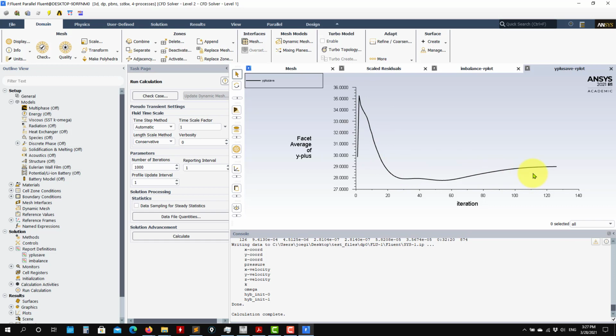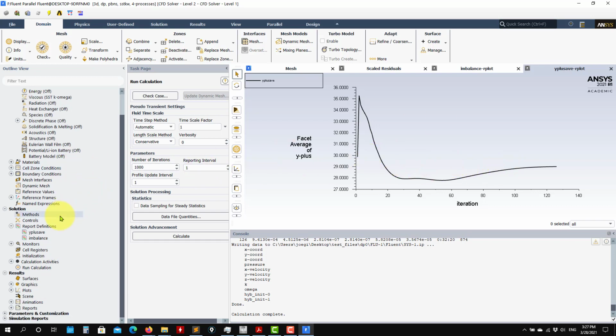In the case of, let's say, aerodynamics, where you are computing forces, you're going to monitor the forces, and if you see that those forces are still oscillating, you need to run those simulations longer, okay? In this case, I will take it for granted that it's a good one, but it is an indication that you might need to run it a little bit longer. So we have a solution, and what we need to do now is just the post-processing, okay?